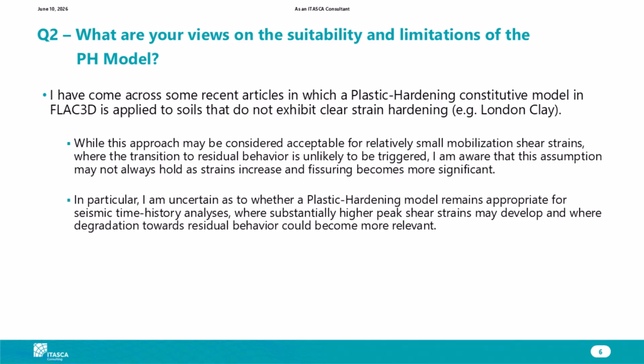Okay, your question here is for dynamic analysis, and for that, I would agree with you that it is questionable unless you're at relatively small strain. To be able to capture the degradation is still useful if you have material that can exhibit hardening all the way up to maybe 5-6%. You probably just need to check that the strain during cycling doesn't really go above that level. So it is more a combination of running the analysis with the tool that we have, because it's still better than doing nothing, but using some engineering judgment, like I'm sure that everybody does, on top of the result that you're getting.